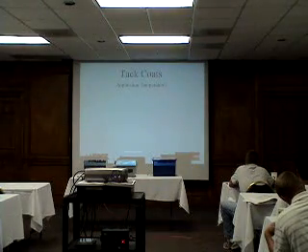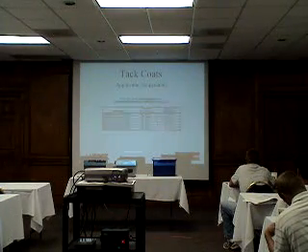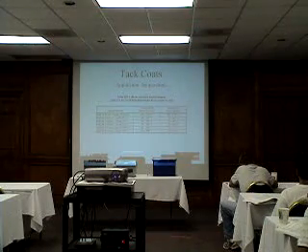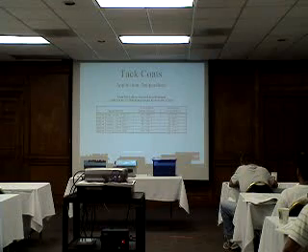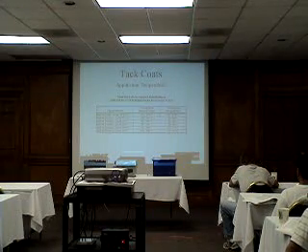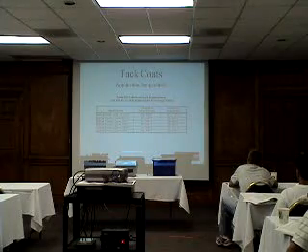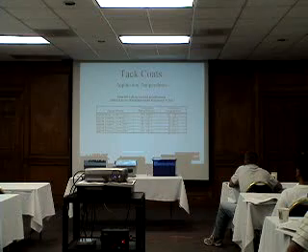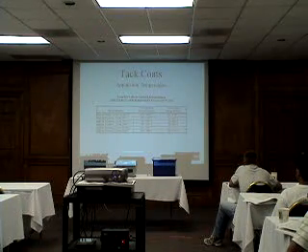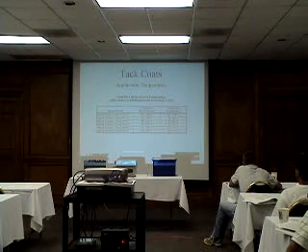The application temperatures, again, here is the temperature range for each grade. Of those 7 grades listed there, which do you think the contractor is going to choose? It's going to be one of these 6 down here, right? These are emulsions.